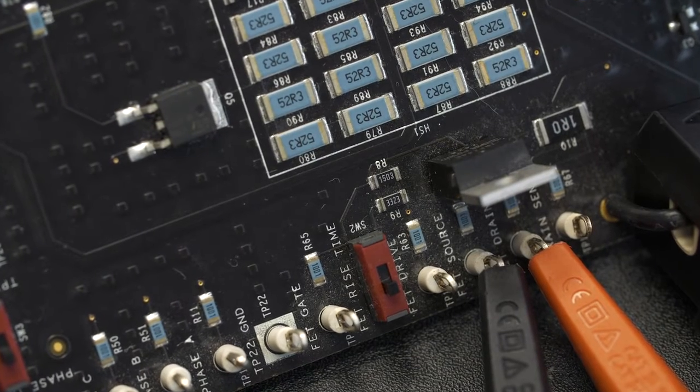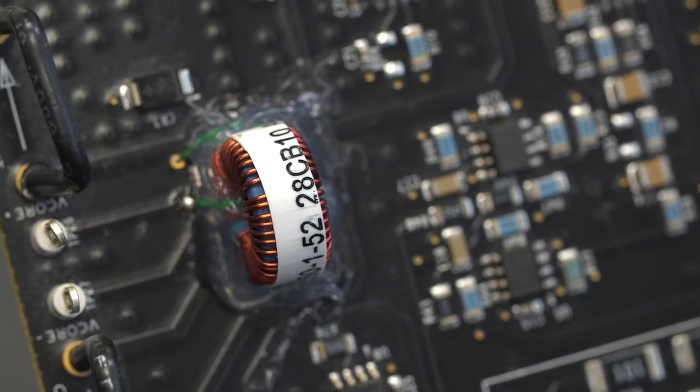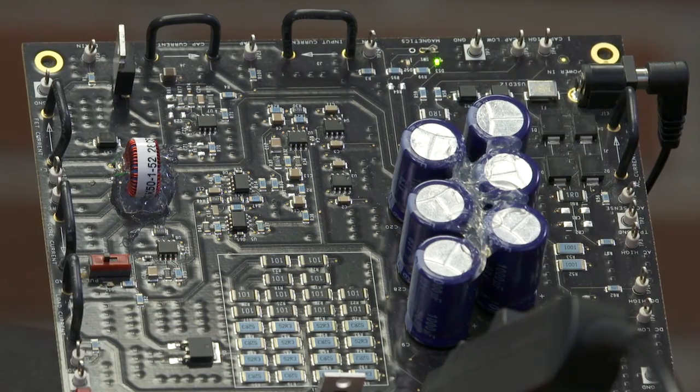Now that we understand the setup for input, output, and power efficiency, let's take a look at some of the component level issues that would cause that efficiency to drop. The primary causes of power loss in a power system are the power switches and the magnetics. Understanding the switching and conduction losses along with magnetic losses makes it possible to optimize the overall efficiency of the system.